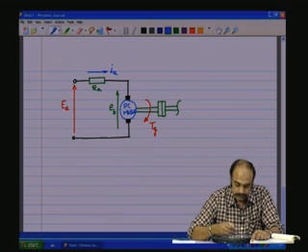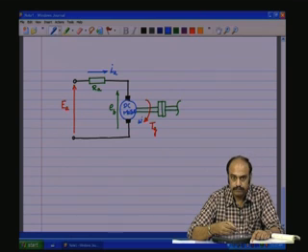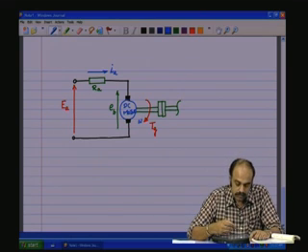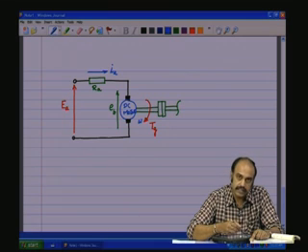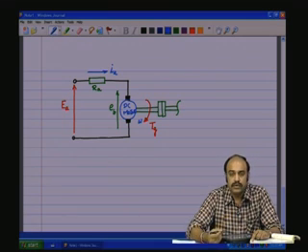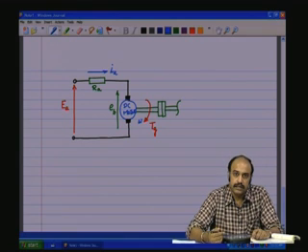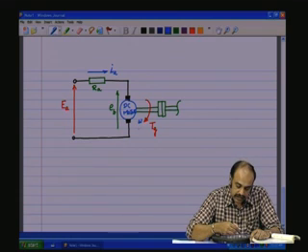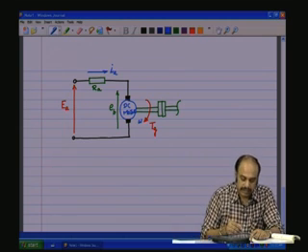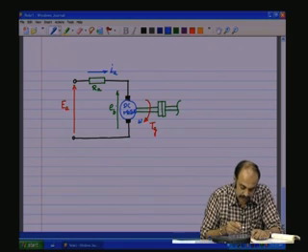If the speed omega here reduces due to some reason like loading, then this will induce lesser voltage across the coils, because the induced voltage is given by P n phi z by 60. The induced EMF is proportional to n, the speed. So, reduction in the speed will cause reduced induced EMF, or the reduced back EMF or reduced counter EMF. This is also called counter EMF in some of the literature.